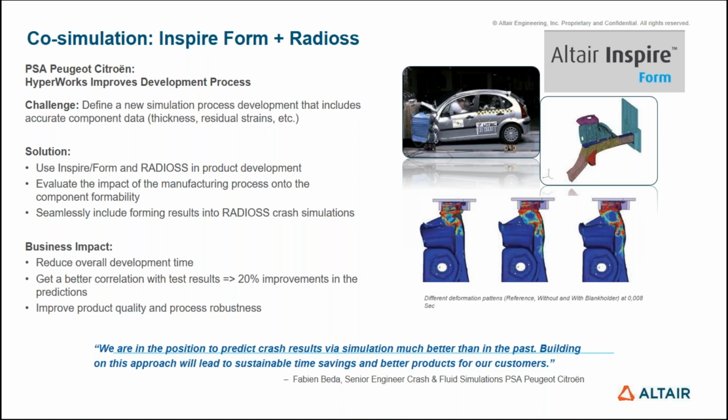During this forming simulation, residual stresses, stresses and strains generally get developed. And if you are not considering this residual stress and strain while doing the crash simulation, then you are probably approximating your predictions, right? Once you do the forming simulation, you can consider those residual stresses and strains in the crash simulation.